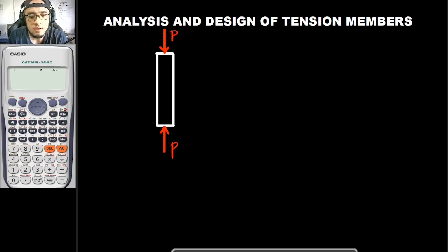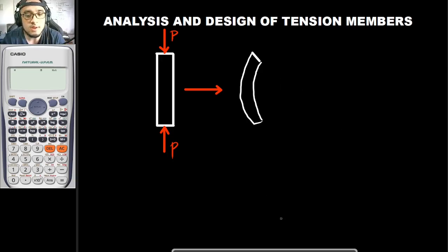Like what I have said earlier, when you are to design a certain structural member, you must first anticipate the manner in which it would fail. And if you are to deal with compression members, the most common failure would be failure by buckling. Its failure mechanism would typically look like this. So it would buckle in this manner. After knowing the manner of failure, you must then design this structural member to resist this kind of failure. And that is structural designing in a nutshell.